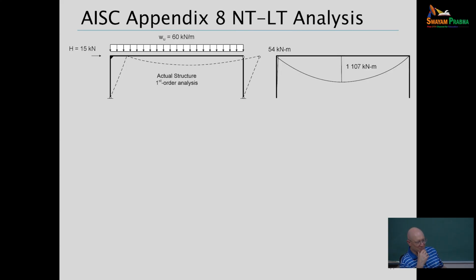There's no thrust coming from the column on the right. So if you have gravity load, in your first order analysis, I have nothing to equilibrate any thrust in the left-hand column, correct? So I have zero shear and zero moment in the left-hand column also, and my moment diagram is simply the simply supported beam moment diagram in the roof girder.